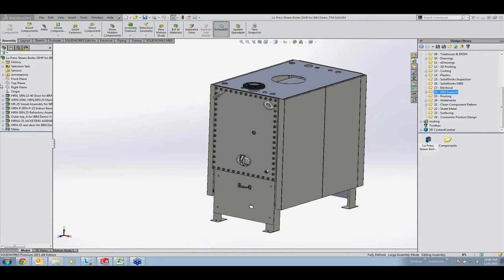But now I can actually make an end cap inside the tube. You can choose an offset here of 10 millimeters. I can modify the thickness of the end cap here. We want it to be 25. Change that back to 5 there. I can also choose the offset for the edges of my end cap here. In this case, maybe 2 millimeters.